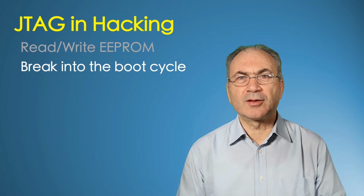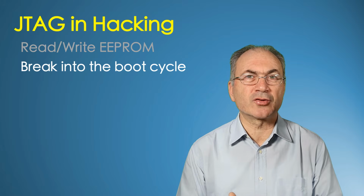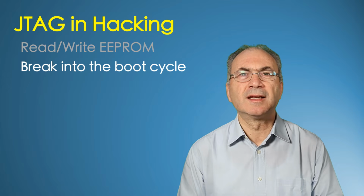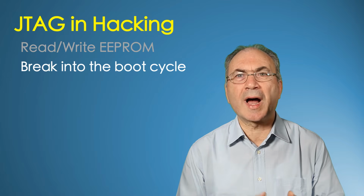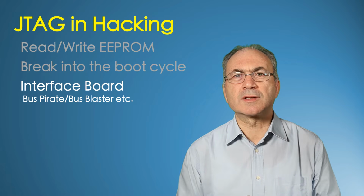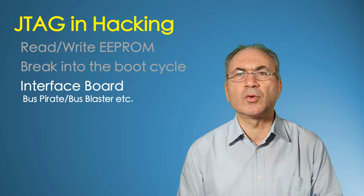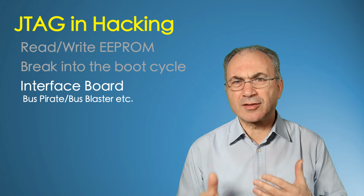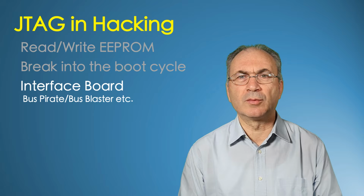Doing this kind of thing is not easy because, although there is a lot of information on the internet on how to proceed, it is quite complicated. And we also need a serial-based interface board to attach a PC to the JTAG interface. The two most popular interface boards in the open source and hacker community are Bus Pirate and Bus Blaster. There are also some other interface boards. Anyway, you will find the links in the description below.